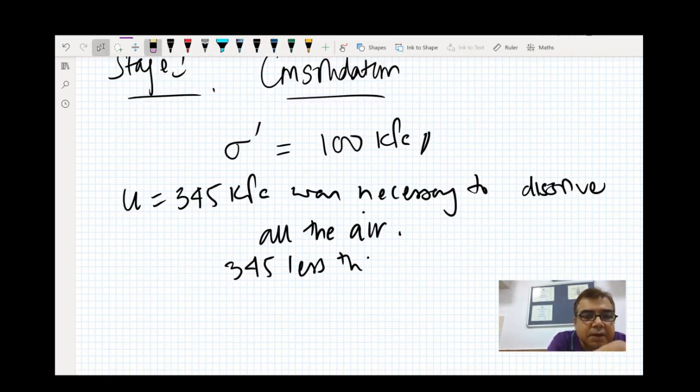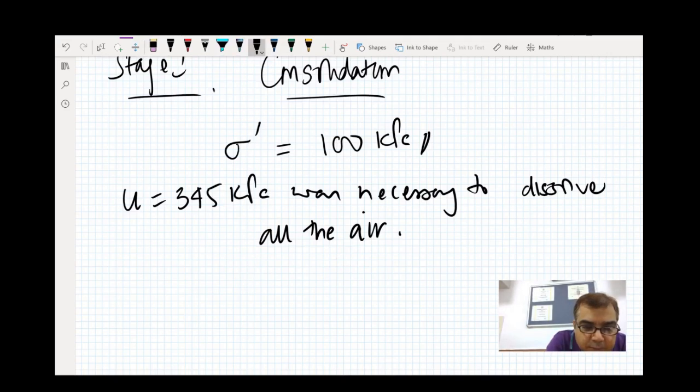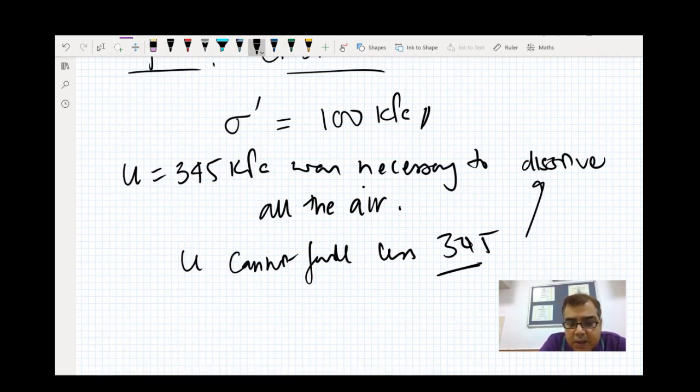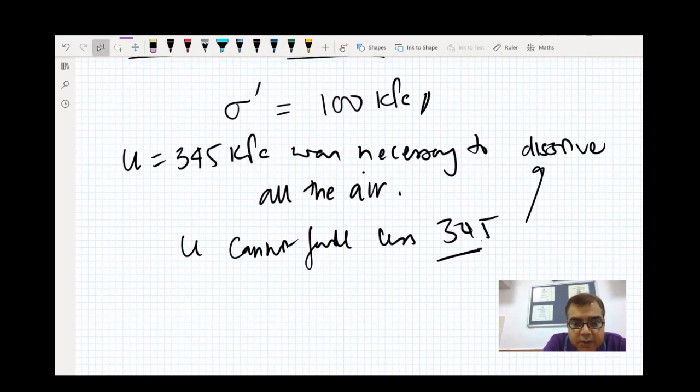In other words, my pore pressure cannot fall less than 345, because anything less than 345, my air which is dissolved will come back. So I need more than 345 of U value.